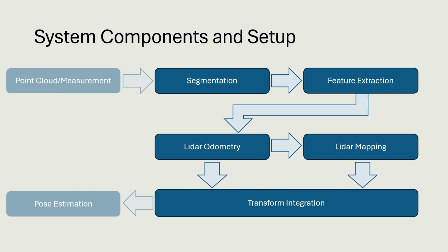LiDAR odometry only works with the point cloud from the previous and the current LiDAR measurements. Therefore, it can be executed at a high frequency of 10 Hz. The determined transform is not very accurate because only a few points and not the complete map is considered.